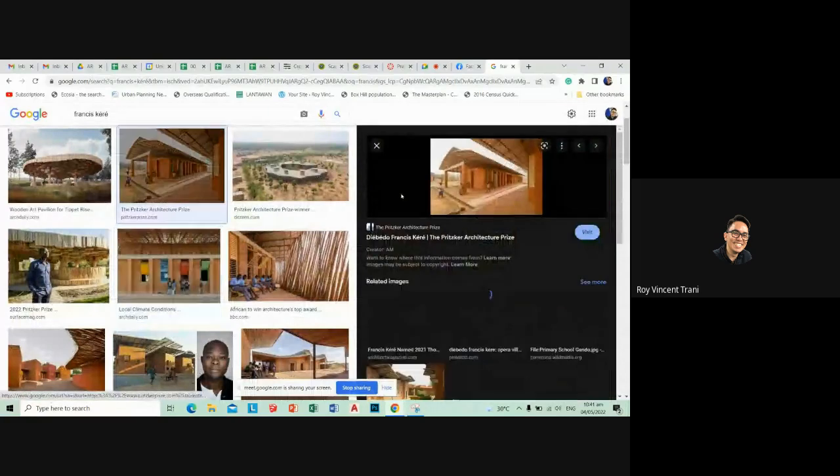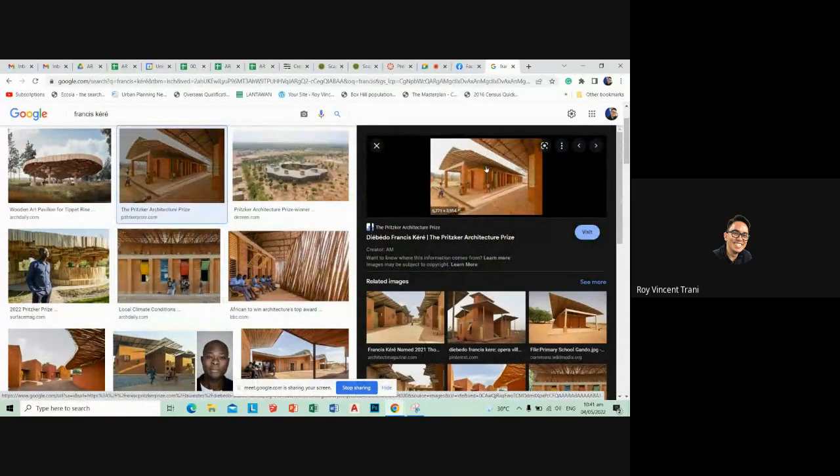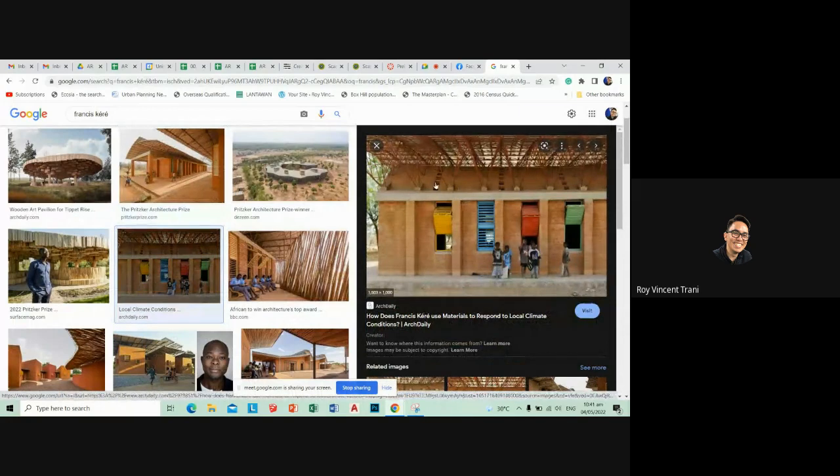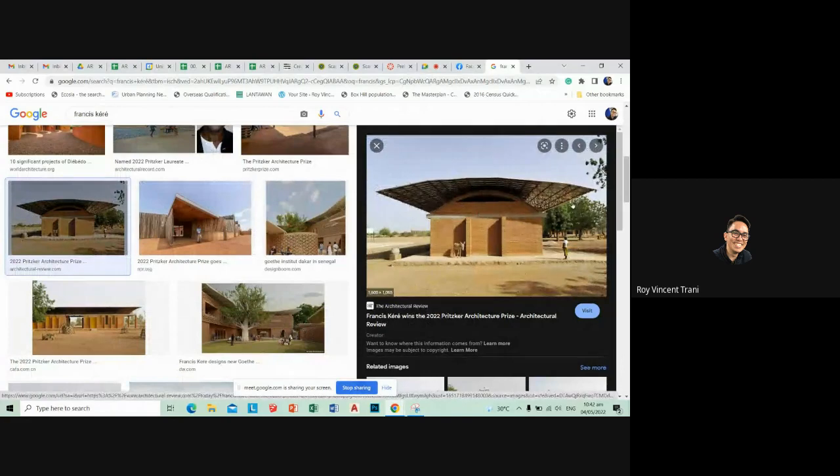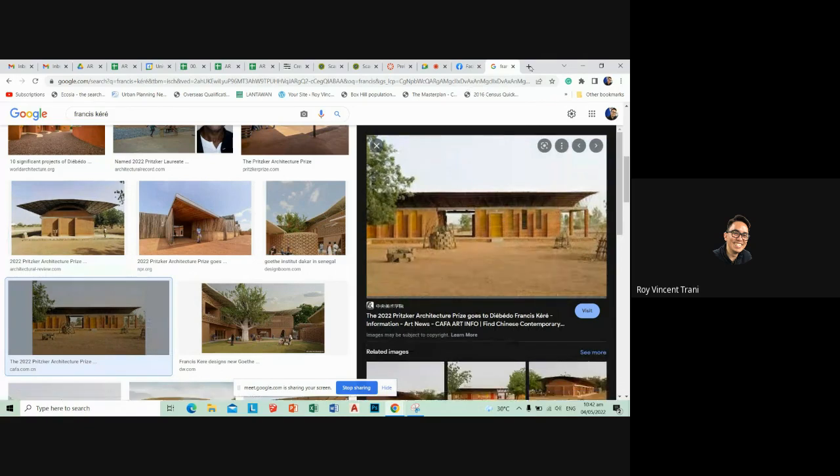Notice the treatment of the roof. It provides shade and also ventilation because there's a layer of brick here for the roof of the building itself, and it's open so that the hot air goes out. The roof itself attracts the hot air because it's made of steel. It gets hotter, so basically above the building is hotter, so the cool air comes in and the hot air goes up. So there's a sort of passive cooling there. And then this is the building in section. Very contemporary, and at the same time it has a very rustic feel with the brickwork. Almost reminds me of Louis Kahn.